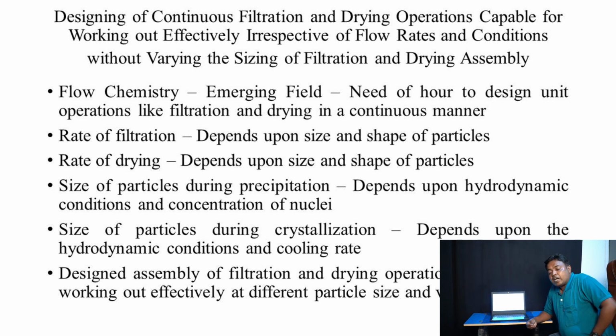Therefore, the system design should be capable of working effectively irrespective of particle size and irrespective of the flow rates. The size of the particles during precipitation depends upon the hydrodynamic conditions and the concentration of the nuclei. The size of particles during crystallization depends upon the hydrodynamic conditions, and in the case of cooling crystallization, it depends upon the cooling rate, and in the case of evaporative crystallization, it depends on the evaporation rate, meaning the rate of generation of nuclei.